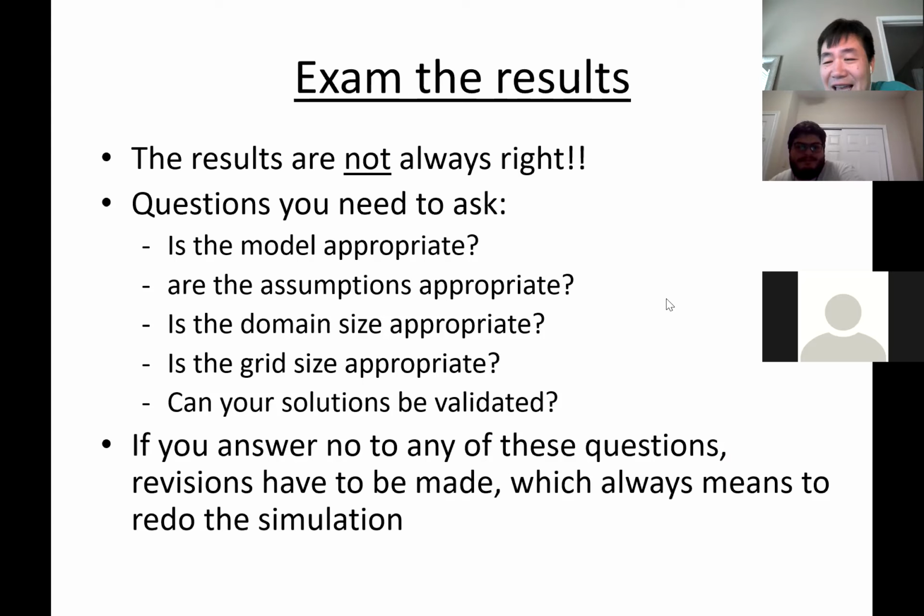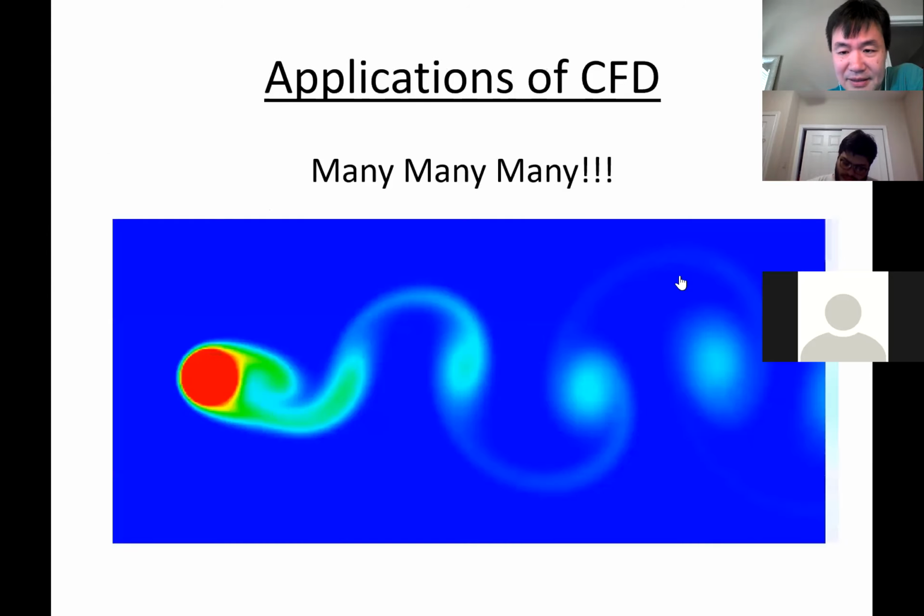You don't have to verify every case. For example, you simulate many cases for the design you want to do. Maybe pick one, or pick an easier one where you have benchmark data or something to compare to. If it compares well, that means for a similar simulation, like the one you compared, it should be fine. Not exactly the same, but similar should be fine. Then at least you will have a little confidence in your work.